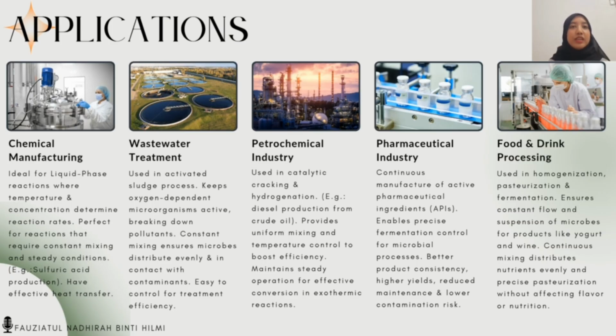The second one is wastewater treatment. CSTRs are commonly used in the activated sludge process, which helps to keep oxygen-dependent microorganisms active in breaking down pollutants. The constant mixing of the CSTR ensures microbes are distributed evenly in contact with contaminants. It is also easy to control for treatment efficiency.